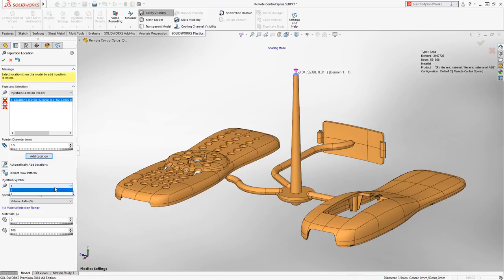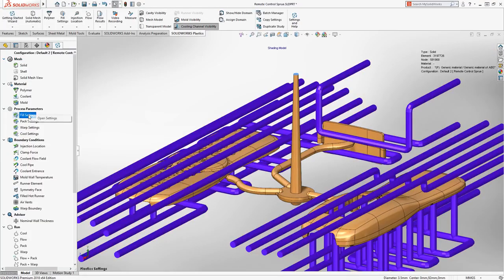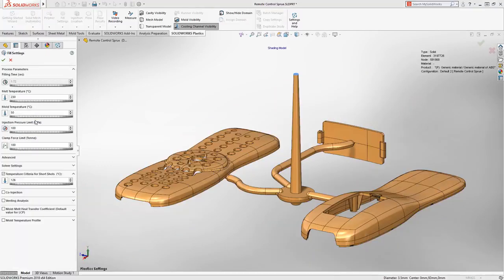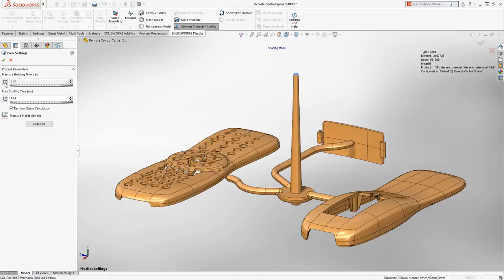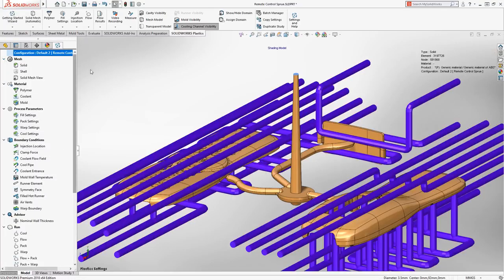Depending on the information you're looking for, SolidWorks Plastics allows you to simulate multiple steps of the entire injection molding process, including flow, cooling, packing, and even warpage. All of these different areas of the simulation process reveal different aspects of the manufacturing cycle and their impact on final parts. Likewise, each of these processes has parameters that you can specify to determine the optimal injection molding parameters.